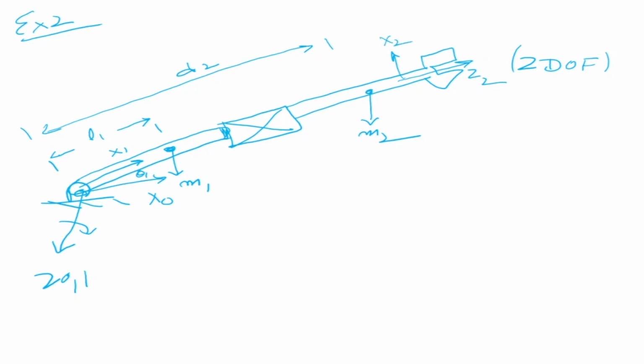That's our second axis. Now understand this very carefully: when this link rotates, when joint 1 rotates, what happens? It can rotate like this or like this. Okay, that's because of joint 1. And joint 2 is a prismatic axis, so it can only translate like this. It cannot do anything more.